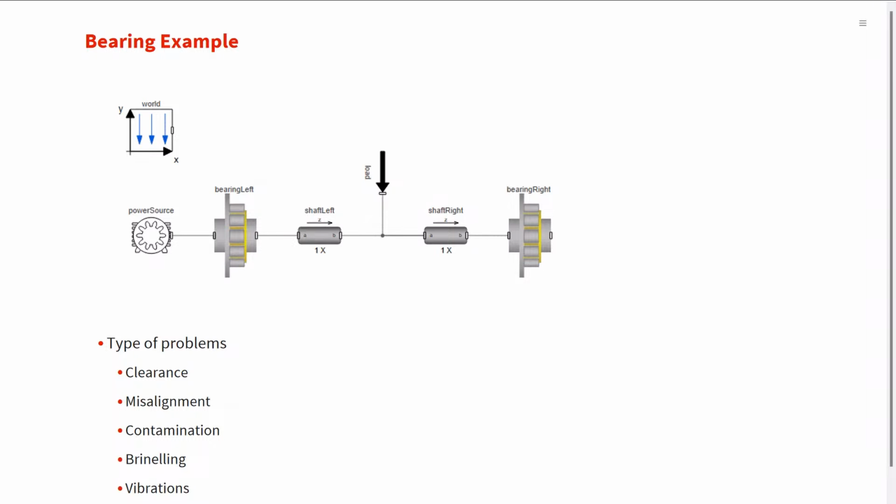And we have, of course, excessive loads, which challenge us to check the stresses on the roller to discern if an overloading force has been applied and pick a bearing size for optimal performance. The presence of a defective bearing in this model, whether due to brinelling or contamination, can set off a chain reaction, leading to vibrations and complications.